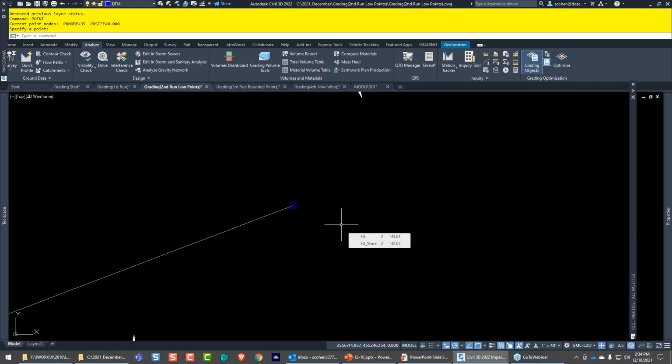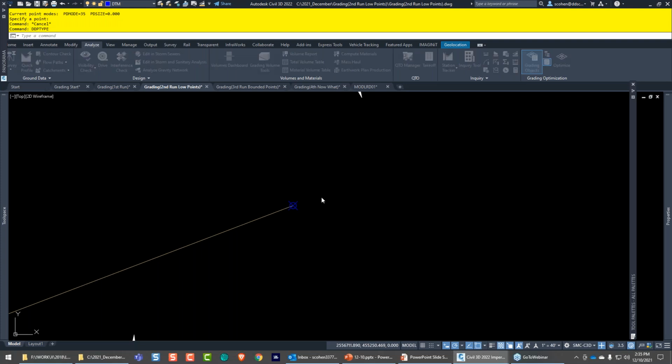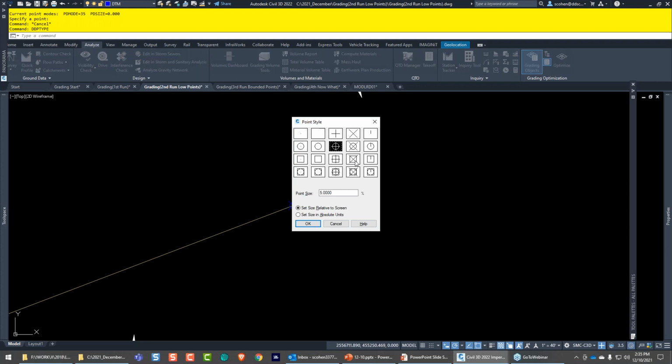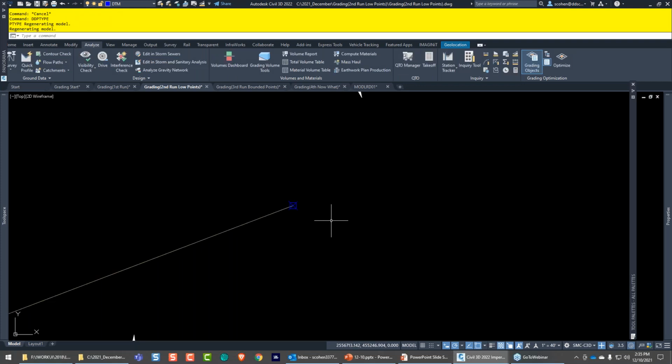I'm going to snap here, that's it. I'm not doing any elevations. This is just flat 2D. Now, just as an AutoCAD tip here, usually an AutoCAD point just shows a dot and you can't see it. So the command, if you want to know how to change that, is DDPTYPE. And then you can change the way it looks. If I want them to be a box with an X, now it looks like that.